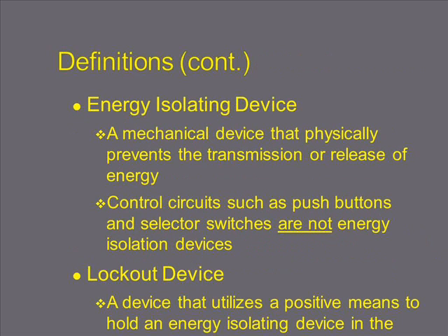Other definitions include energy isolating devices. This is a mechanical device that physically prevents the transmission or release of energy. Control circuits, such as push buttons and selector switches, are not energy isolation devices. A lockout device is a device that utilizes a positive means to hold an energy isolating device in the safe position.